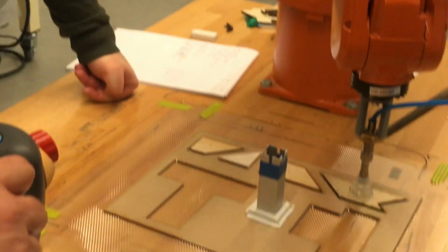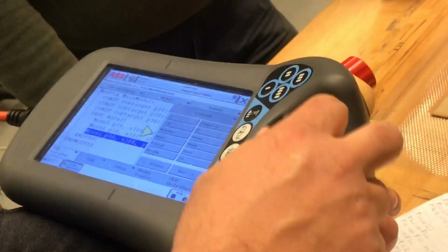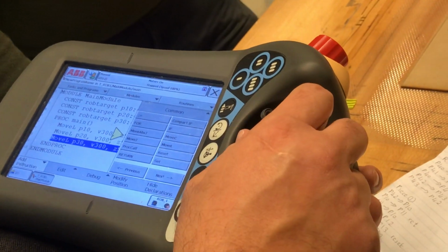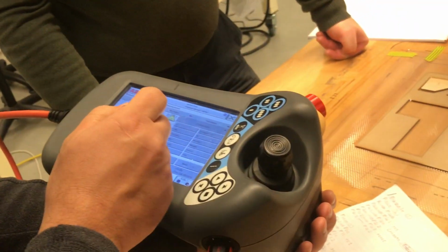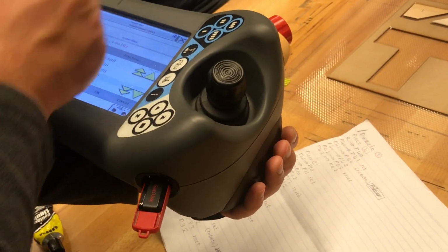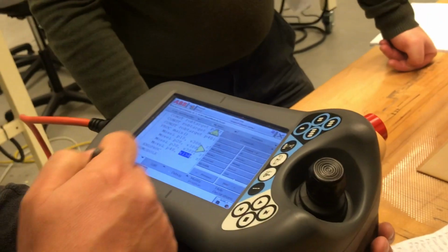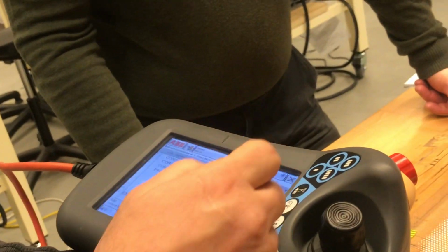And I have to go down to that position. Move linearly to this position. Then go down to pick the part. Move linearly to this position. Now this last movement should go to 100 or 150 for the speed. I will use 150. Now I'm going to do the wait time, set, and wait time.